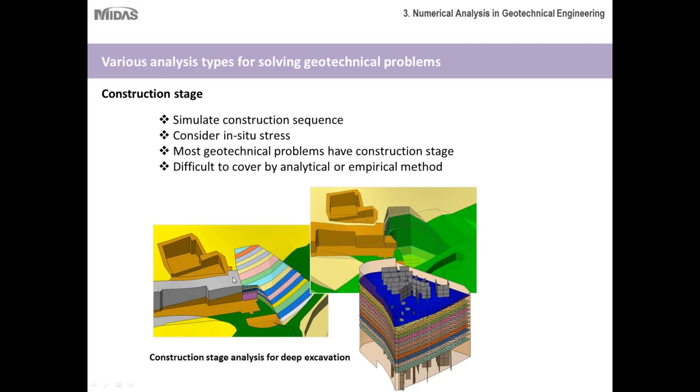affect the nearby structures. For example, this nearby foundation, this nearby retaining wall, I believe there's a street over here. So you can see gradually how the stability of these neighboring foundations and structures was influenced by the excavation. And then likewise, as the foundation itself was created, you could account for temporary support structures. You could see how the loading on the foundations increased over time. Also, you can see how the loading upon the soil increased over time. You could account for nonlinear behavior for the various layers.